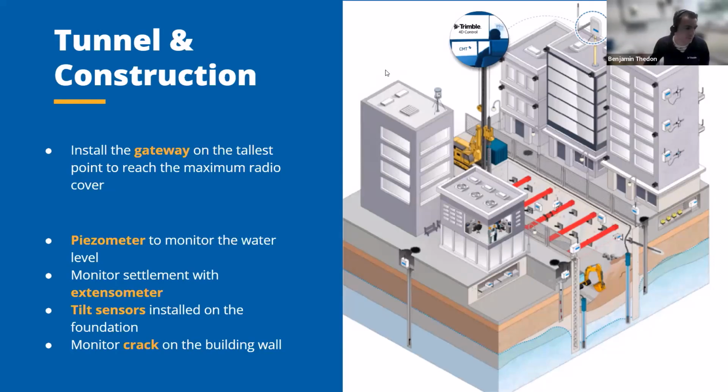You can also use some piezometers to monitor the water, to make sure you are not flooding your excavation or your foundation. Also an option is to monitor with IPI your foundation itself, to make sure that when you dig your excavation, there is no change on your foundation. And some crack meters also, to monitor the cracks, to make sure your excavation project doesn't have any impact on the current cracks in your building.